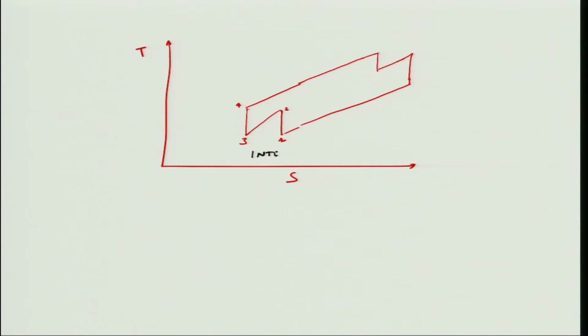So this is intercooling, and this is an example of reheat, and this particular amount will be Q save. So this is nothing but Q regeneration, and this is going to be reheat. This is your primary heat, this is your energy saved. So you can clearly see that this would lead to a better or more efficient gas turbine.